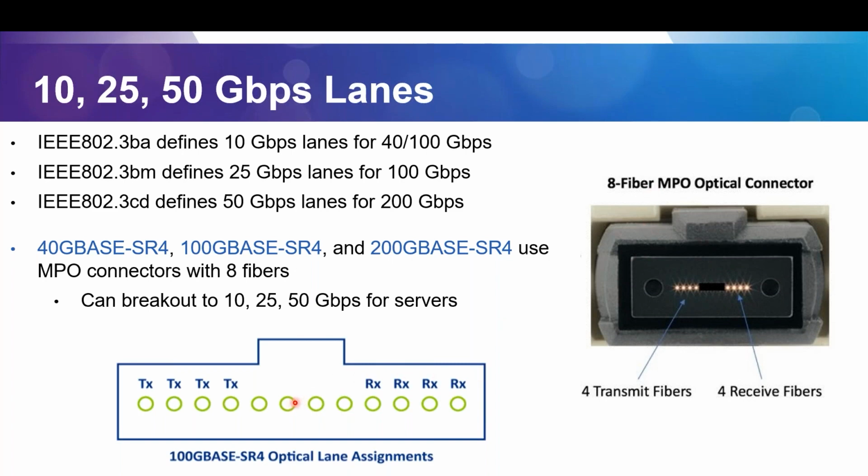So one of the things to keep in mind, if you're working with some manufacturers, they've got 8 fiber solutions that are out there. Now, Corning's got their Edge8 solution. What that is, there are no fibers in the middle here. So if you're testing a fiber cable, your tester doesn't realize that there's no fibers in the middle. So it's going to run a test and it's going to fail. It's going to say, hey, fibers 5, 6, 7, and 8, in this case, they're completely broken or extremely dirty.